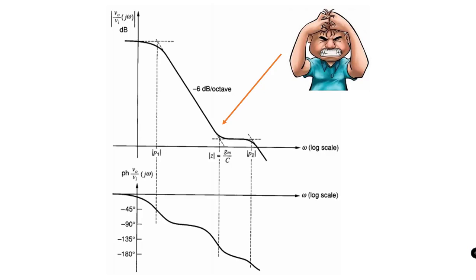So all of this happens due to the existence of 0 on the right half of the S-plane. To avoid the 0 from coming in between the dominant and non-dominant poles, one has to understand the origin of this 0.